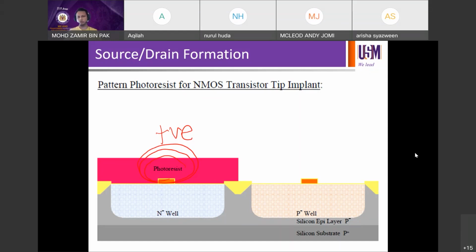So you want to expose on the right side so that the resist is soluble and then removed during the development process, CED, right? Removed during the development process, and then you're going to be left with patterned resist on the left to be able to do this pitch, right? So now you end up with patterned resist on the left. So what we're going to do next is